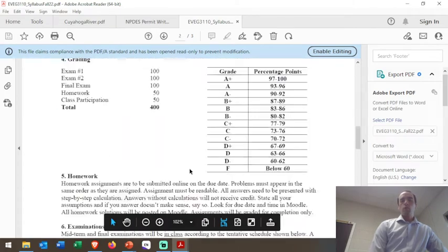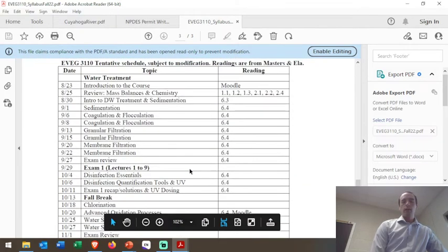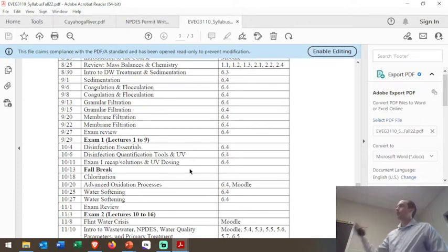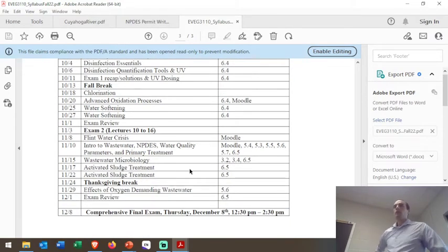Then we went and covered the chemical aspects. So that's kind of where we are. We touched on the physical mass balance stuff that applies to everything, went into the chemical side. Those are the categories we use for drinking water treatment. And then for wastewater treatment, we also use biological processes. So we get the physical, the chemical, and the biological. We don't typically use biological for drinking water, just not normally needed.